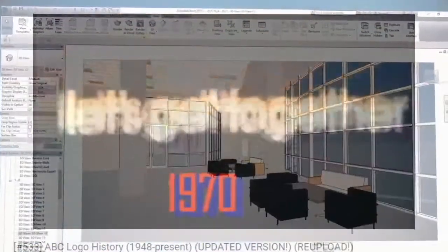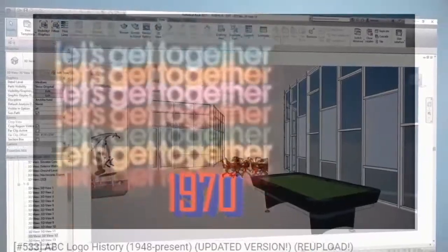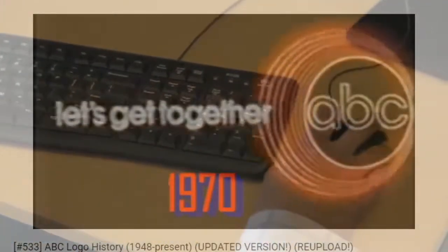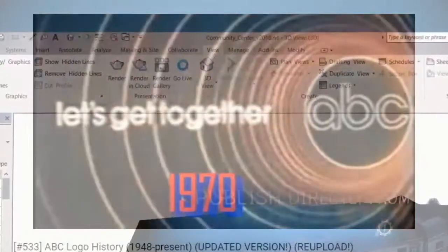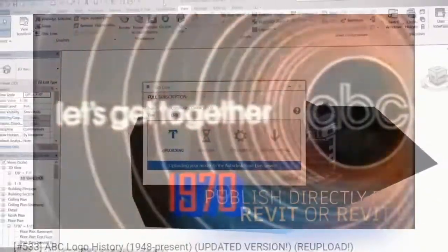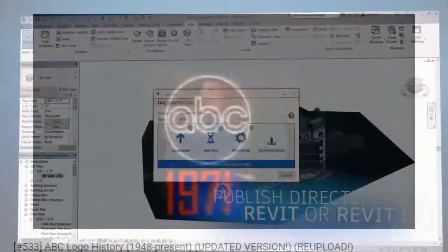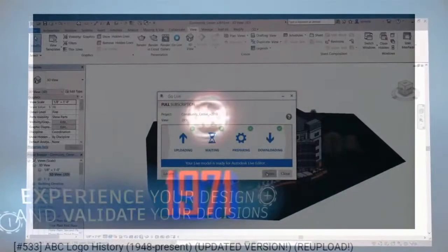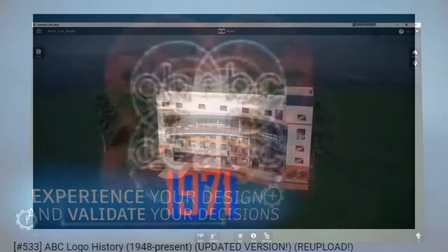Finally, if the structural requirements allow a thick finish to be applied to a floor without dropping the structural slab, a finished floor element can be modeled directly in place within the structural slab, as shown in figure 14.21. The tile floor has been graphically embedded in the structural floor using the Join Geometry tool. To do this, click the Modify tab in the ribbon and click Join Geometry. Be sure to pick the finished floor before the structural floor or you'll get an error.